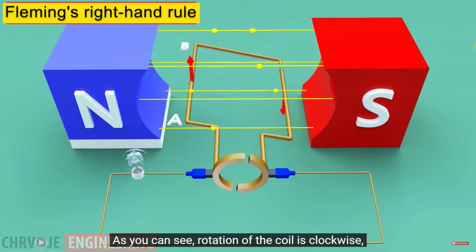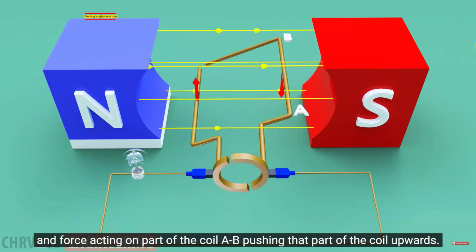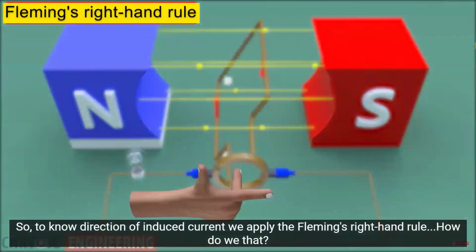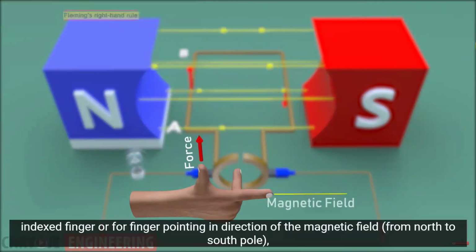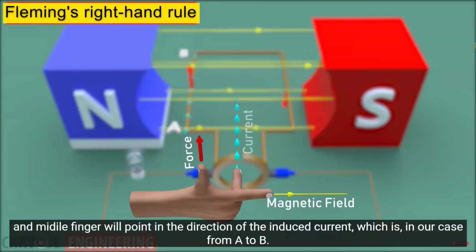As you can see, the rotation of the coil is clockwise, and the force acting on part of the coil AB is pushing that part of the coil upwards. So to know the direction of the induced current, we apply Fleming's right-hand rule. How do we do that? We place our right hand so that the thumb points up, showing the direction of the force. The index finger points in the direction of the magnetic field from north to south pole, and the middle finger will point in the direction of the induced current, which is in our case from A to B.